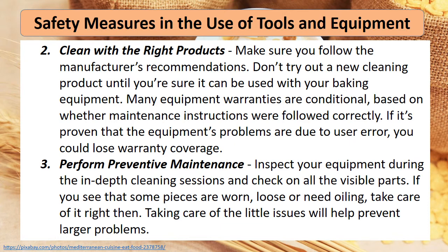Number 3, perform preventive maintenance. Inspect your equipment during the in-depth cleaning sessions and check all the visible parts. If you see that some pieces are worn, loose, or need oil, take care of it right then. Taking care of the little issues will help prevent larger problems.